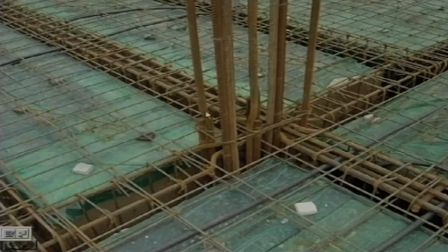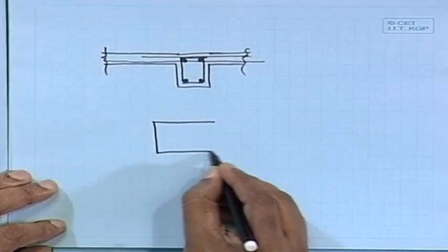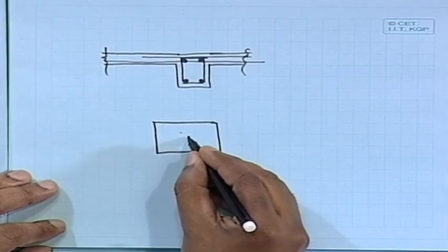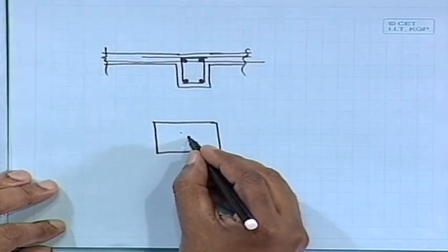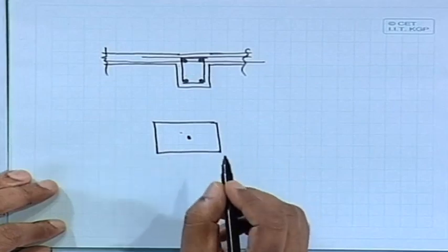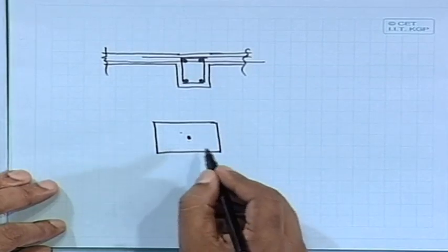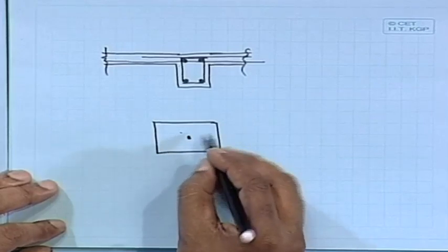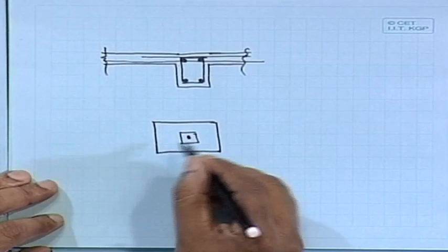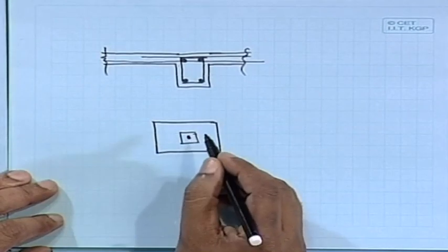So, first of all, the load is applied. In our case, it is simply axially loaded, for the time being let us consider it axially loaded. But even if it is not axially loaded, say for example, if this is a column cross section, I am talking about the plan, how far shall we allow? It is the ideal case that the load is applied here, axially loaded. But that is not possible. Even if you go from the ground floor to the top floor, maybe the second or third floor level, due to construction also it will deviate a little bit. So, how far shall we allow this eccentricity, so that though it is theoretically not, practically it is an axially loaded column?